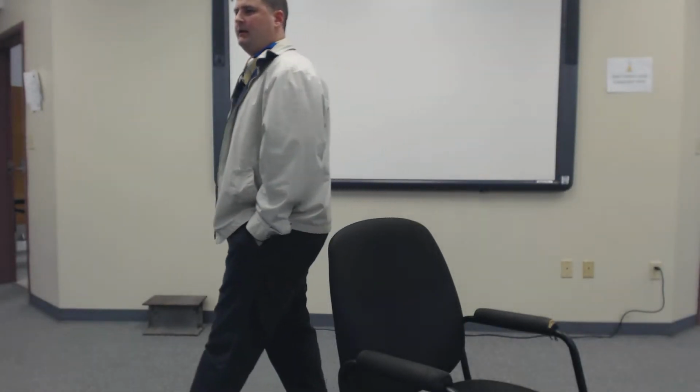And then, of course, I make my framing members that are sitting up on top of my wall a unique line system and use that all the way through. You'll see I actually use a phantom line. Two dashes, then a big dash, and two dashes, and a big dash. That's just what I use. Some people just use solid lines to represent them. I try to use it so that when you look at my plan, you can tell the difference from one thing to another.